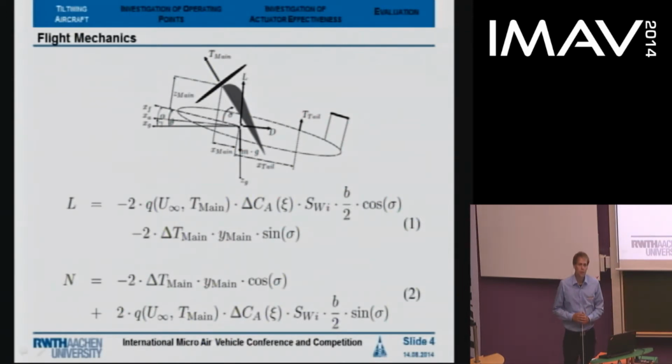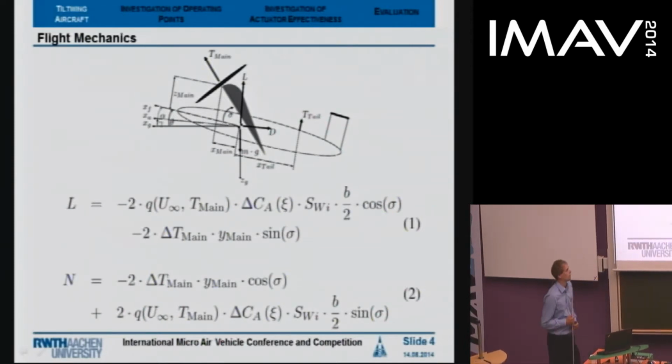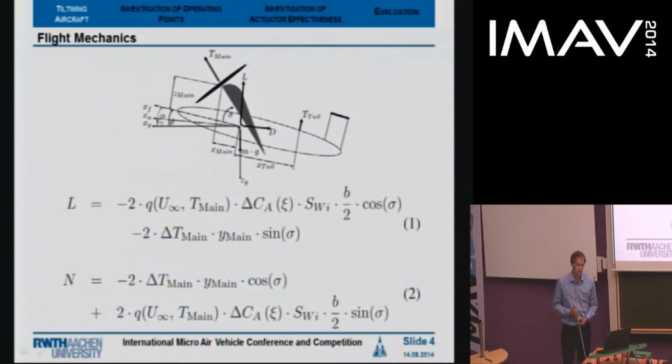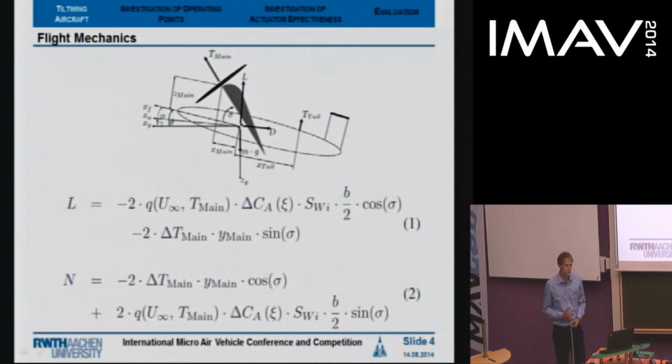Additionally, not only the direction is changing, but also the magnitude of both actuator effects is dependent on the current transition state, as it's dependent on the tilt angle and the dynamic pressure. So it can be stated that the lateral movement is heavily coupled, and additionally we have some nonlinear effects like stall that cause instabilities too. And because of all these effects, the transition is often performed as a continuous process.